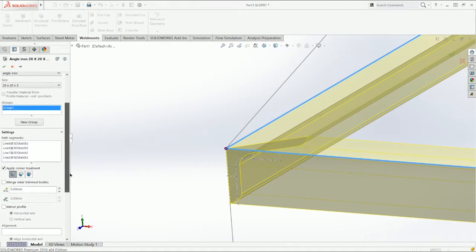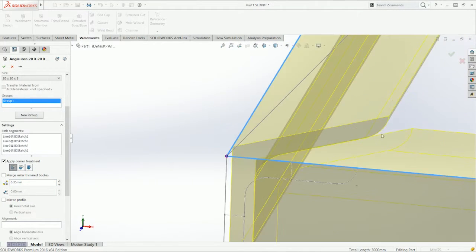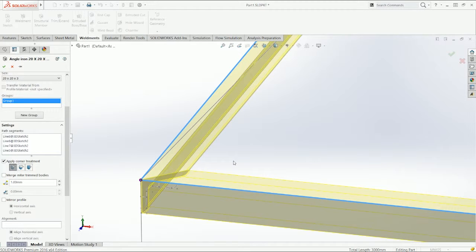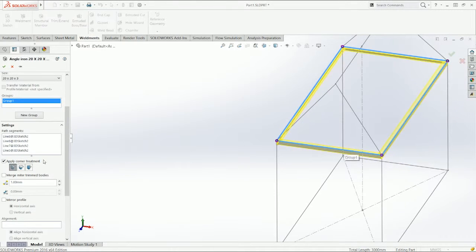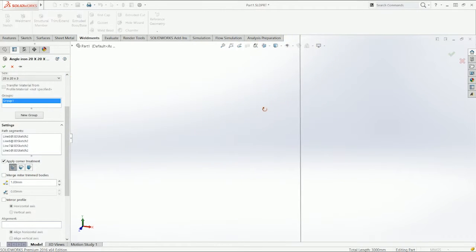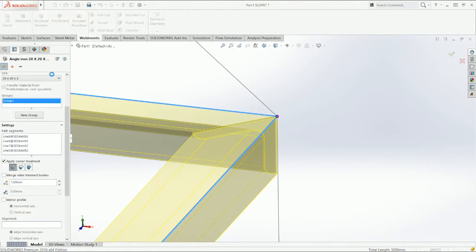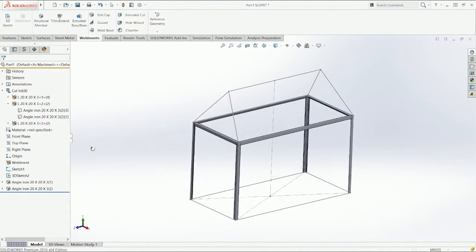And also you can add a weld gap, which is usually a quarter of an inch or something like that, which you can put there. So that just leaves a space between them, so the weld is possible between them. So I just set 1 mil right here, so it is easier for everyone to weld it. And since I did that, that's going to leave a little weld gap between all the parts, as you see there. So I'm just going to click OK here again, exit the isolation so I can see the whole structure, and keep working from here.